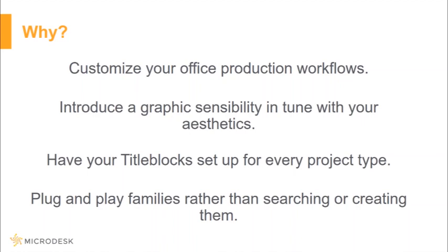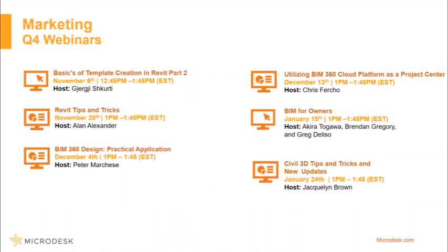And then finally, we have plug-and-play families. Why do we do this? Well, we don't want to go and search for them. We don't want to create them on a tight project deadline. So if we have some base but very powerful families, we can throw them into the project, and then eventually we'll build off of them rather than have to start from scratch when we have a tight deadline.